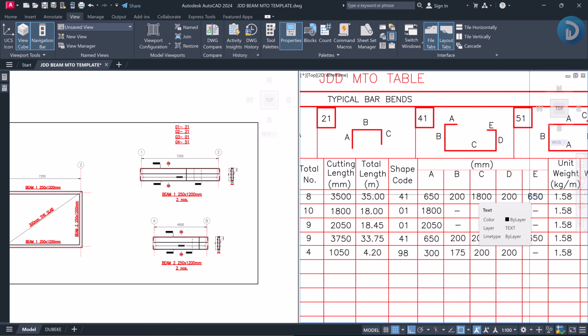So I can have a reinforcement having 12 meters of length, but if I cut 6 meters from that respective reinforcement, I'll be able to achieve my bar mark 01, right? So for us to calculate this, we have to sum up the different parts of this reinforcement that is required as specified by your shape code chart, right?